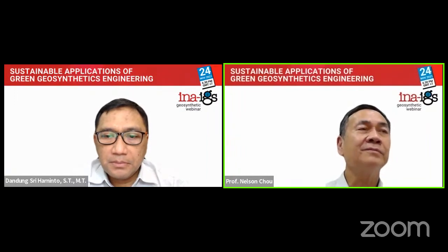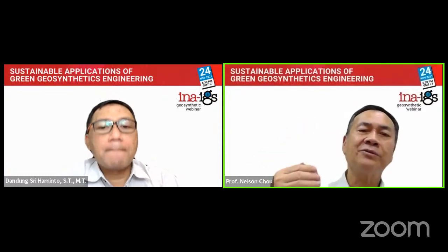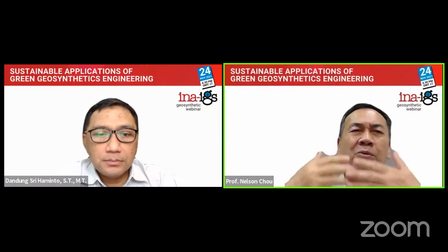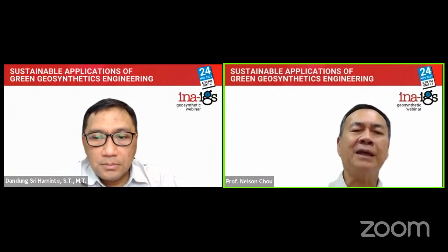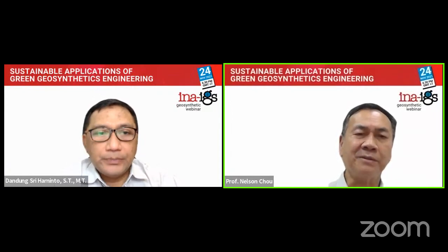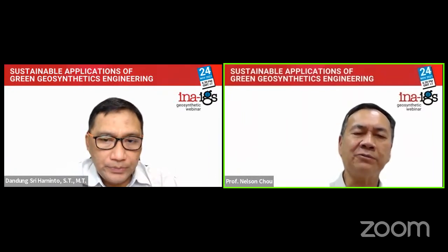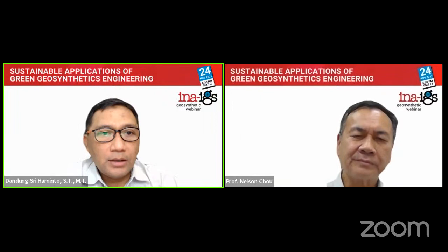In Japan, with the three-art method, the geosynthetic wall was covered with concrete facing. Right after the earthquake, the wall itself stood very well, but it settled. You just cannot avoid settlement. Settlement is a soil behavior underneath. So you cannot reduce settlement, but you can reduce differential settlement. Yes, exactly. Actually, differential settlement is what we're really concerned about, not settlement. Yeah, that's correct.